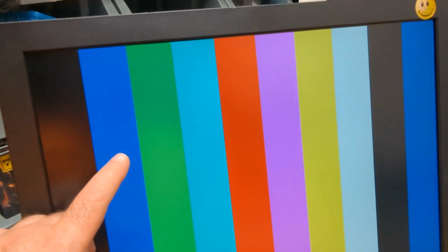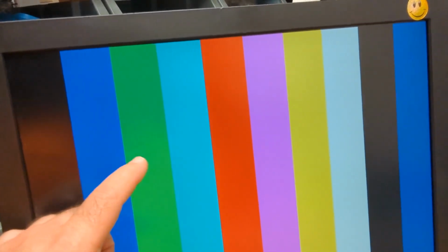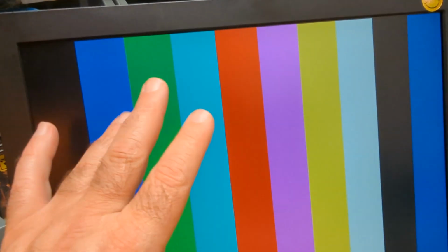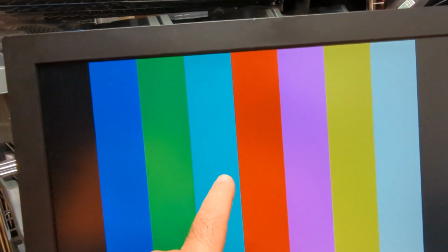So the blue bit is the only one on right now. And that's when we have an 001 coming out of there, and that makes sense. Then when we add 1 to that and it goes to 2, I have 0, 1, 0. So if they're plugged into red, green, and blue, what happens is the least significant bit of those top 3 goes back to 0, and only the middle bit is on. So that's green, right? And then the next one is 3.